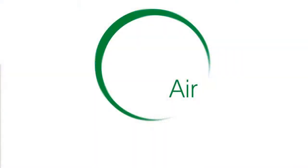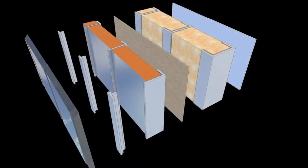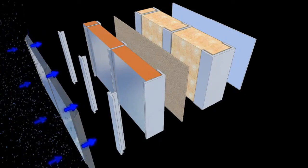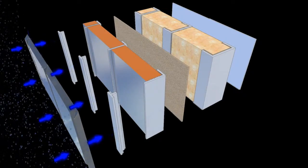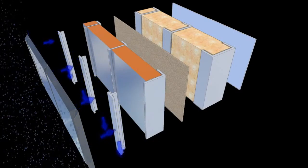The final element affecting our building design is moisture management. Controlling and managing the moisture flow in a building is fundamental to the core principles of HAM and also to maintaining the durability of the building envelope, maximising energy efficiency and protecting the health and the safety of the occupants. There are a number of potential moisture sources affecting all building envelopes, the most obvious being the external environment, weather and rain. Most rain screen systems commonly used in high-rise residential and commercial construction are not designed to provide a complete barrier to water ingress. Therefore, the cavity behind should be provided with the provision for drainage to the outside, and care should be taken at design stage so that water may not track into the inner layers.